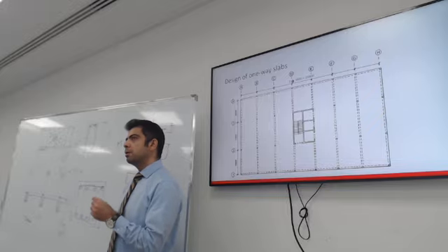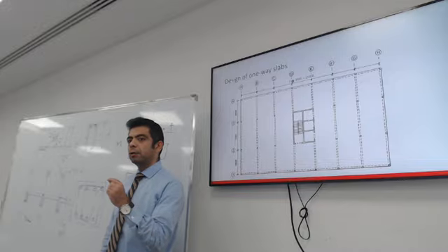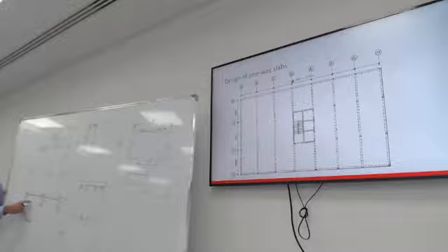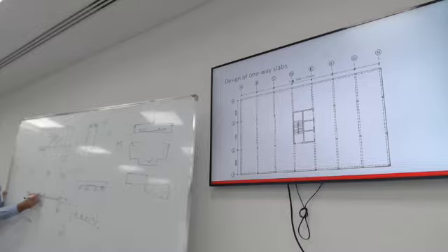You might get away with one layer of reinforcement. You might get away with just the bottom bars. So there's a bottom reinforcement here and bottom reinforcement there. If the thickness is bigger, when you get to a 200 millimeter slab, 250, you need two layers. You need bottom reinforcement and top reinforcement. Even for the one layer, at the supports, I need top reinforcement.